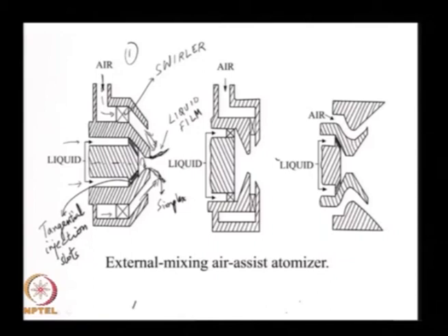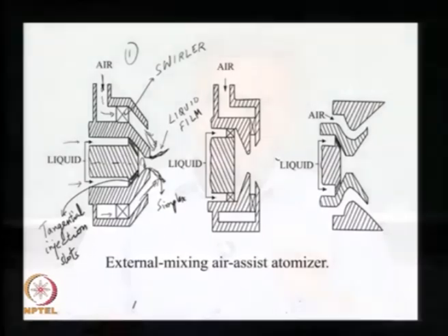This impacting by high speed air is primarily responsible for atomization. So, a design like this will typically operate at liquid supply pressures on the order of less than 1/10 of a bar. So, it is very low liquid supply pressures.